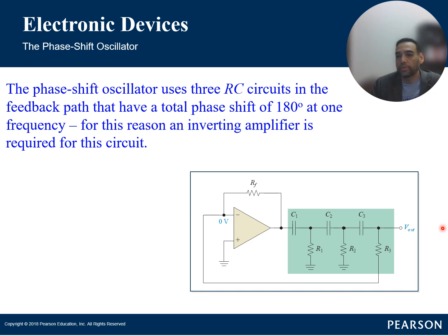Well, let's go back to the components. In the feedback network portion, the heart of that phase shift oscillator is the feedback network, and that introduces phase shifts to the output signal, just like we mentioned before. So that part isn't any different. The abstract operation of the feedback oscillator. Again, the network is made up of multiple RC components, resistors, capacitors. Each stage, in this case, introduces a phase shift in the signal, usually around 60 degrees, at some desired oscillation.